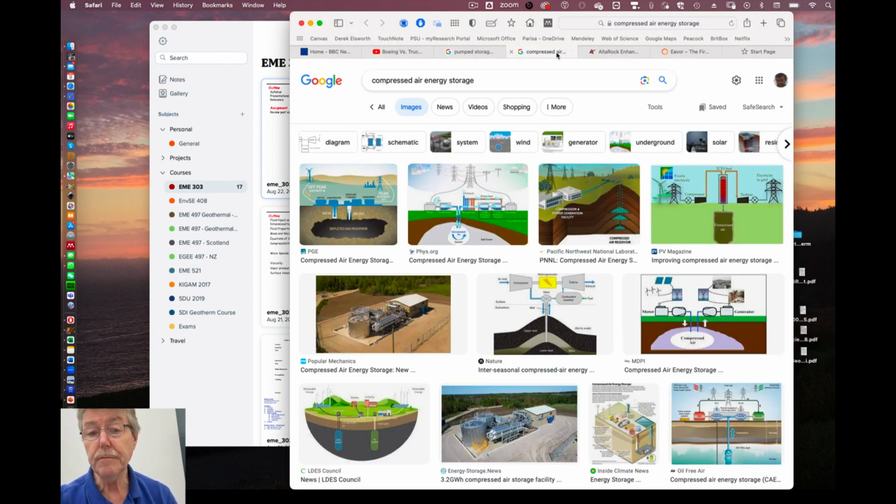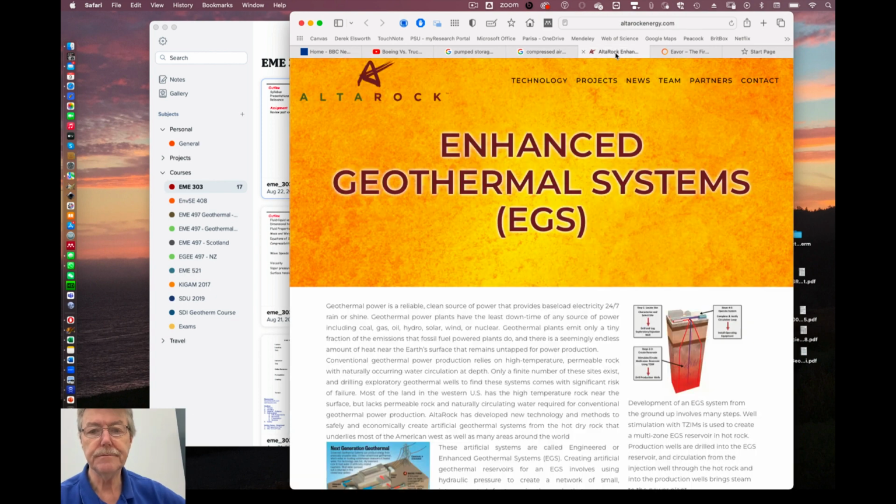Compressed air energy storage is another one. You have caverns underground. You pump them up by compressing air in them when you have energy to spare, and then you run the compressed air back through turbines to recover the energy, just like a big geological battery. In northern Pennsylvania, there are salt deposits, and those salt deposits are made into caverns by putting a borehole down, circulating brine at the bottom, and then retreating the casing up. So you have this big cigar-shaped cavern that may be 1,000 feet tall and a couple of thousand feet deep, that is able to withstand these pressures.